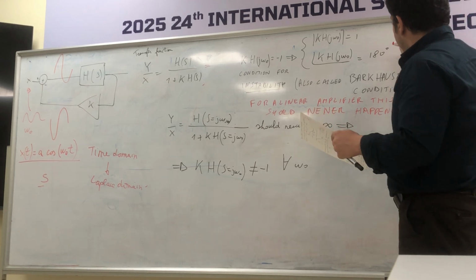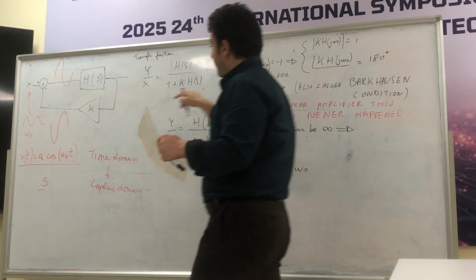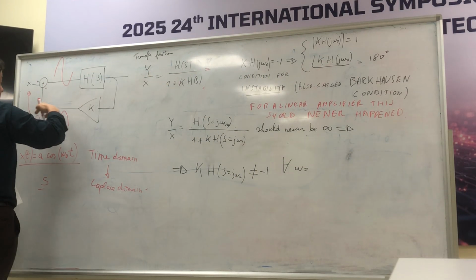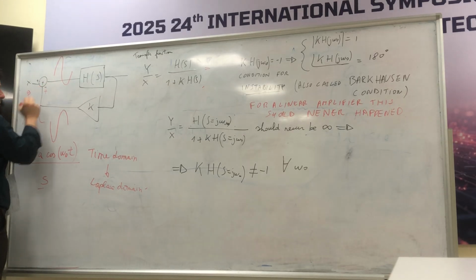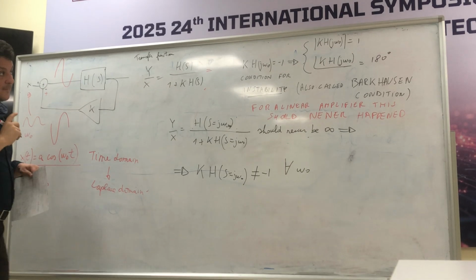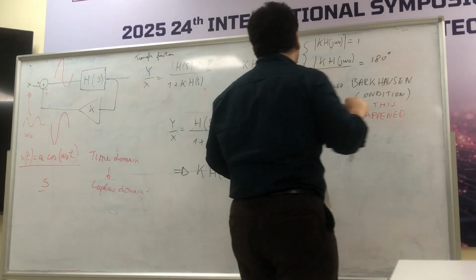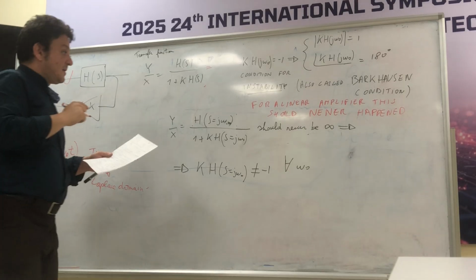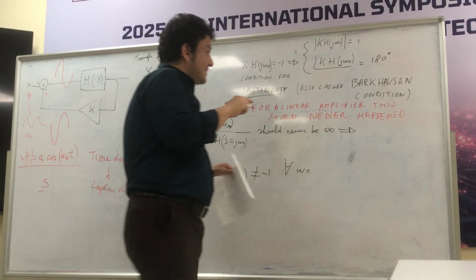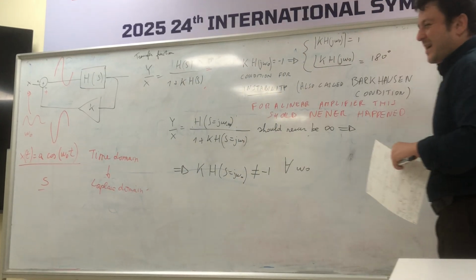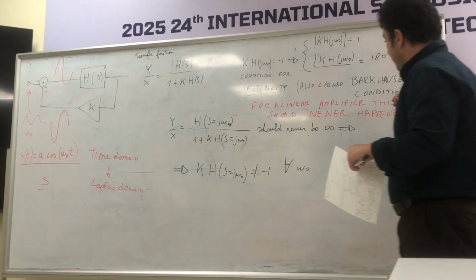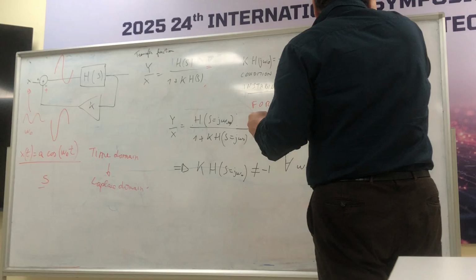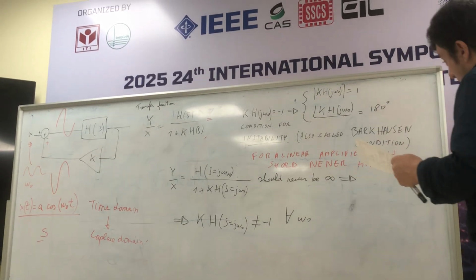Actually we would never want this condition, okay? Because if this is exactly 180, actually it is opposite. It's not a negative feedback anymore. This kind of became a plus, okay? But in order to not let the system diverge, this actually not only should not be equal to 1, but usually should never be larger than 1, or equal to 1.